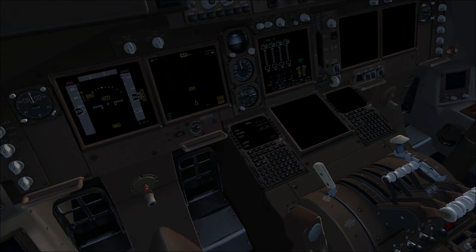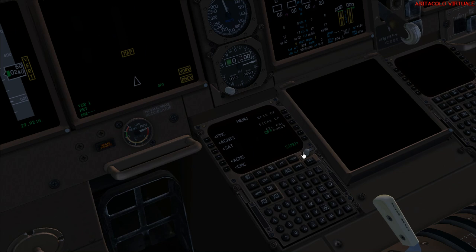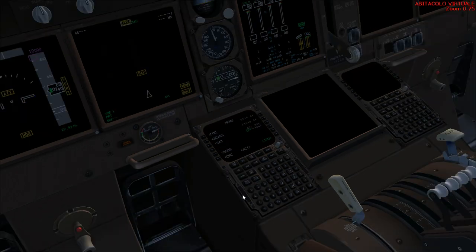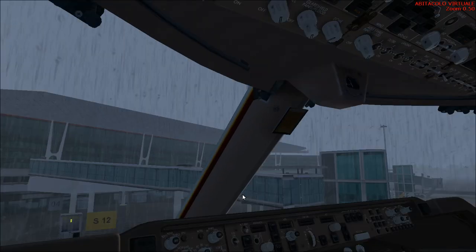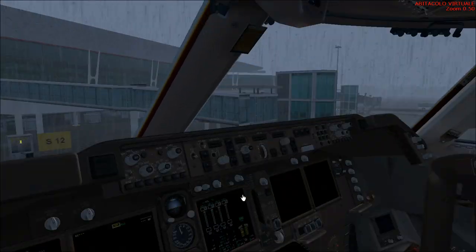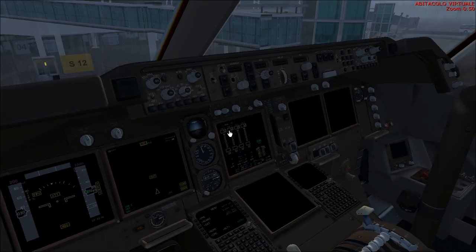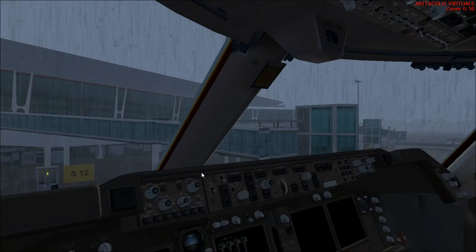Back to our flight, we have to set up the ground power. So we go to the SIMU menu, next page, ground support, ground power, and connect. Back to the normal menu, we can go up on the upper side of the aircraft. We can also set up the screens for the ECAS, for the synoptic actually on the inboard side, but I will show you later.